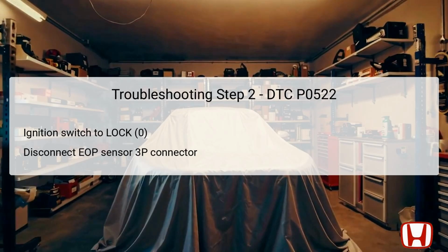By detaching the sensor connector, you can evaluate whether the sensor itself is malfunctioning or if other components in the circuit are the source of the issue. This isolation is an integral part of the troubleshooting procedure, as it allows for focused diagnostics.